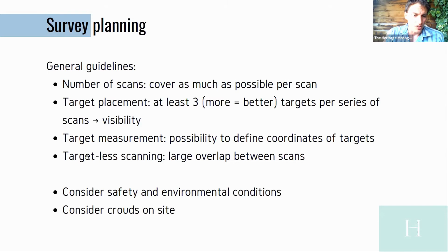Two very important guidelines as well are that you have to consider safety and environmental conditions. Be sure that if you use your total station, it is safe to use it and that you're of course allowed to use it, but I think that goes without saying. But it should also be safe for both the operator as well as the scanner itself. Look for a stable ground, don't look for very steep slopes and stuff like that. And always consider crowds, so people walking around on the site.